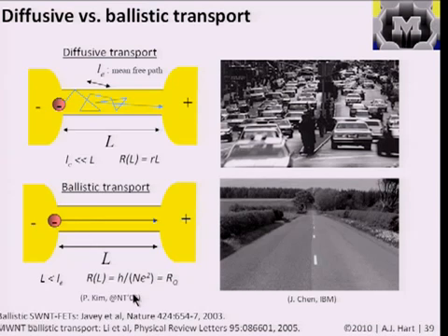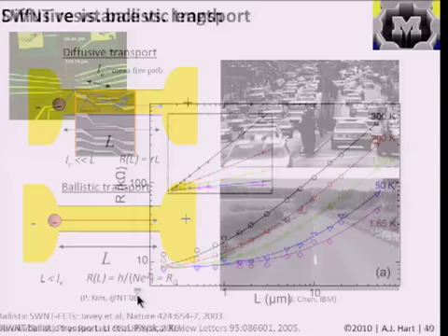For example, it's been shown quite beautifully that in a multi-walled tube you have many conduction channels, and the number of conduction channels available, or the number of lanes for electrons to transport without collisions in the material, has been related to the diameter and the other characteristics. Researchers measured the current-voltage characteristics of an individual tube, and showed that this multi-channel ballistic transport theory applies and relates precisely to these constants and to the specific value of n.